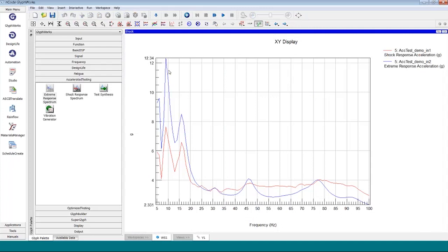Obviously, we'd expect to see peak G overloads if we're truly creating a highly accelerated test, but keeping this within bounds is a necessary way to ensure that we don't end up with just a plain straight HALT test, for example, where the idea is just to break things under extremely accelerated shock levels.